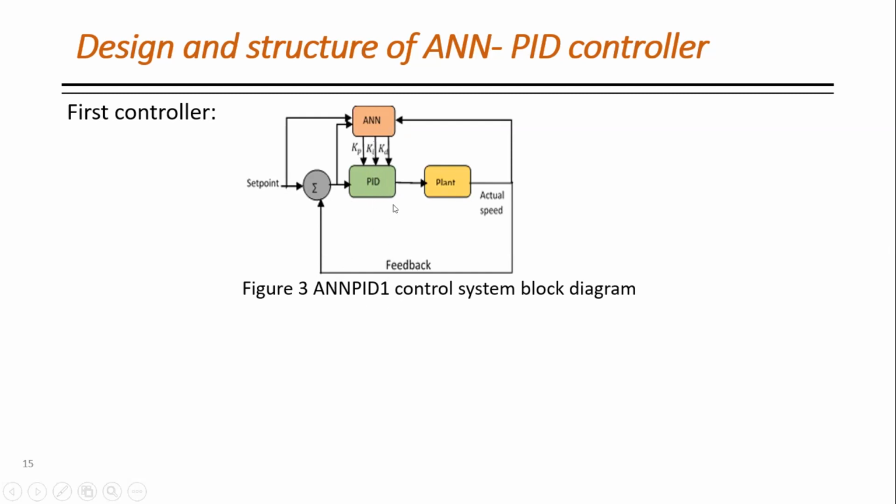In short, it incorporates the advantages of neural and PID controllers. Traditional PID directly regulates the controlled object using a closed loop, while a neural network adjusts its control gains, KP, KI, and KD, based on the system operational condition to achieve a performance optimization.